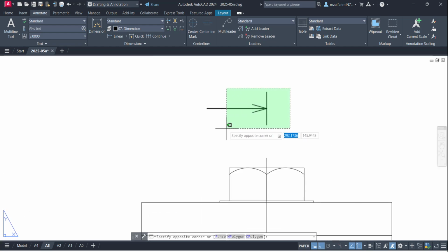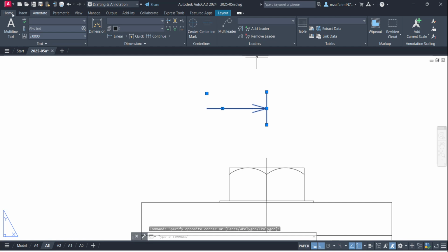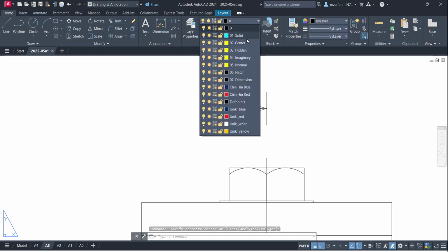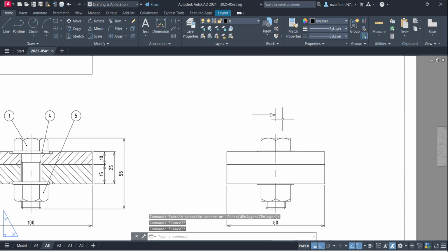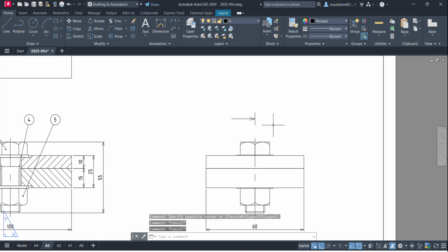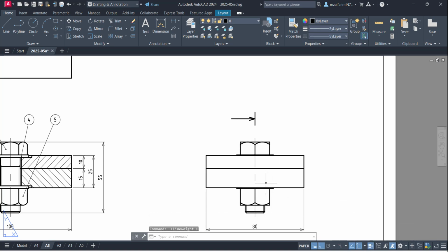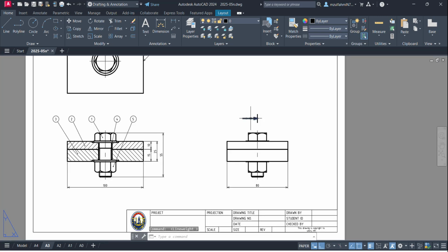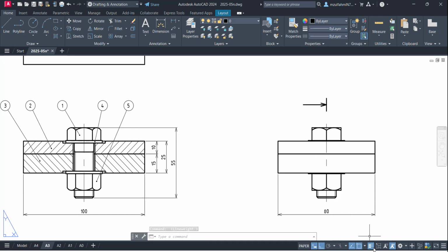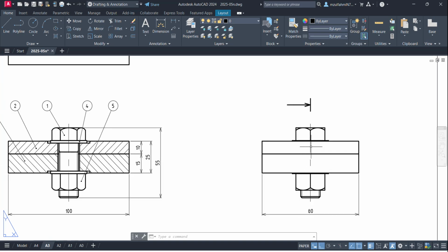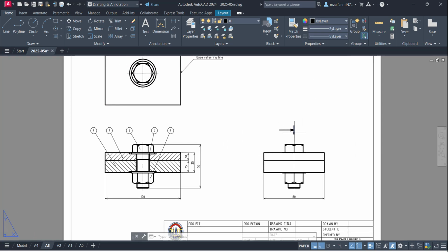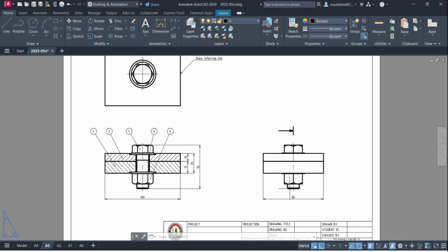Okay, so select all of this and put it in solid line. If you click here, display, it will become a thicker line here. So this will display line weight display. When you print, it will print this thicker.